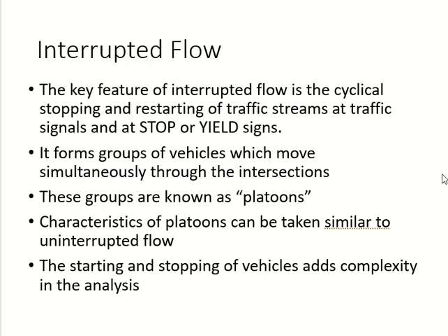The maximum of density and the maximum of speed, are they at the same point? No, they cannot be. How can you have maximum density and the speed is still maximum? Remember the parking lot example. And the critical values, are they maximum values? Just because I am saying capacity, everything doesn't become maximum. The speed is maximum, the density, no. Okay? Clear?